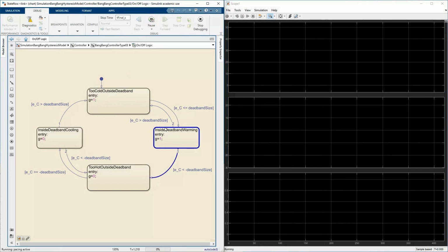Okay, now we're too cold. Oops, wait a second, sorry, where are we? Oh, no, sorry. Right now, we haven't hit the step response, we didn't introduce it yet. Okay, now we said heat up, heat up, heat up. So now it's too cold, it's heating up. Now, aha, it's going to hit the deadband. We're inside the deadband. Oh, and look, the noise pops you in and outside of this deadband, but again, it doesn't matter because it's at G equals 1, right? And now we finally get to the other side of the deadband, and again, we're out here, but you're chattering back and forth with G equals 0, so again, it's not mattering.